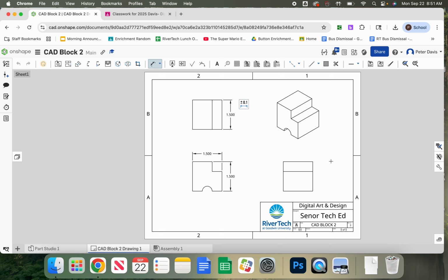On this one, I'm going to add the radius of this tunnel here. And let's up the complexity. We've got a little bit of time. It's been so easy. So you'll notice when I add in the dimension for a tunnel, it gives it to me as a radius because it's not a hole. Circular holes are dimensioned by diameter. Arcs like this are dimensioned by radius.